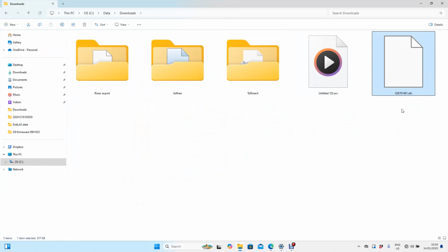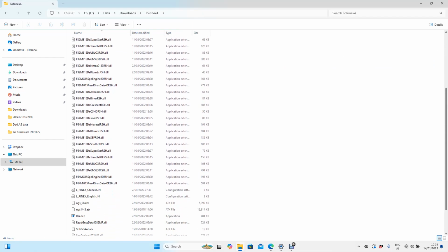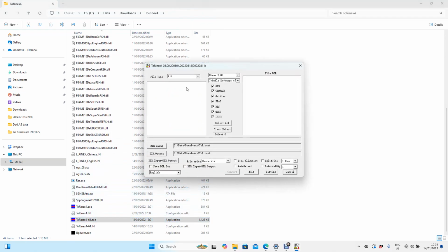So at the moment it's in a South format, it's proprietary. So obviously if you've done it in RINEX already, it's just going to be a RINEX file. But what we'll do is, if you have it in South format, you can use this free utility software. You don't install it on your PC, you just copy the folder over and run it directly from the folder. There's no physical installation. I'm running a 64-bit machine. So it's just a little simple utility software.